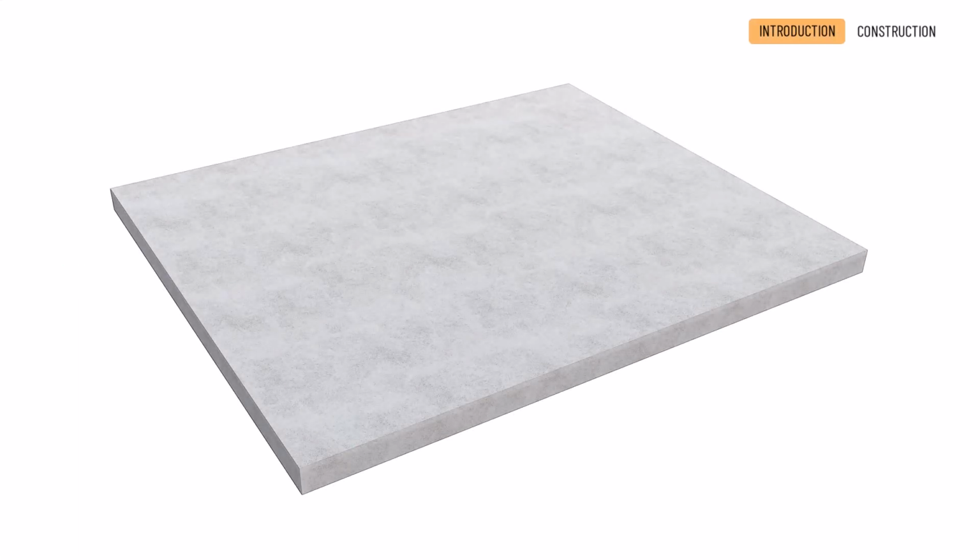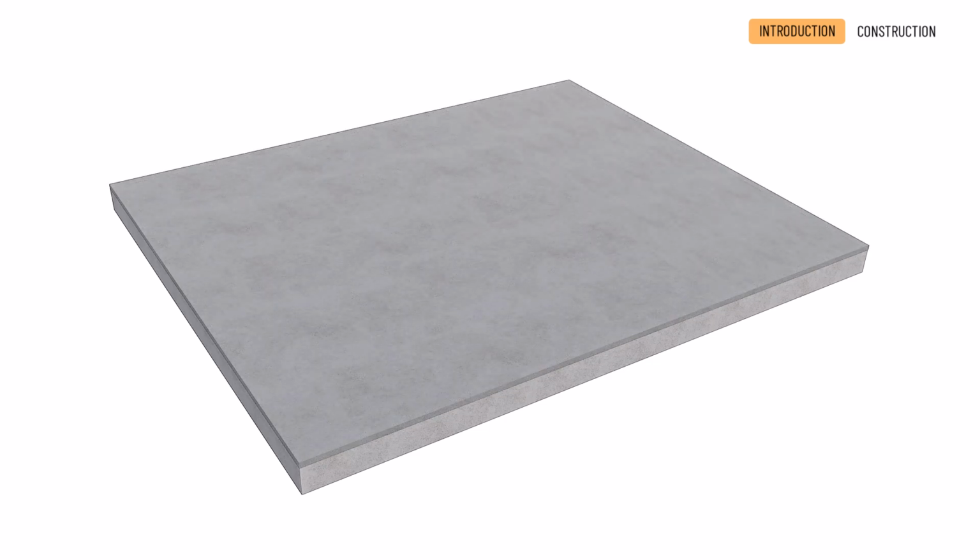Subfloor for floor finishes. Floor finishes or coverings are rarely applied directly onto the slab or the floor slab. Firstly, a solid, even-surfaced, flat and smooth subfloor is prepared on the structure to provide a suitable base for the floor covering. The subfloor may consist of in-situ concrete,